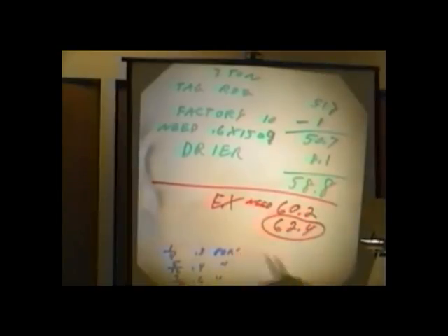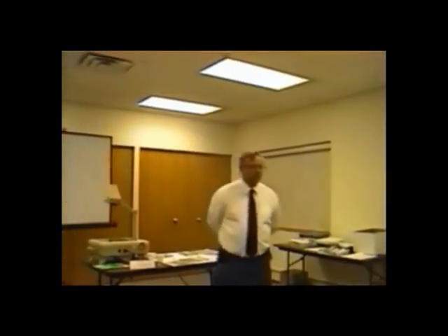This is what you need. And the system was already charged with 62.4. So you'd have 2.2 ounces too much in there, correct? How are you going to recover 2.2 ounces? Just leave it in. Why? You got your plus or minus 2 ounces. Exactly. Leave it alone, you're done.